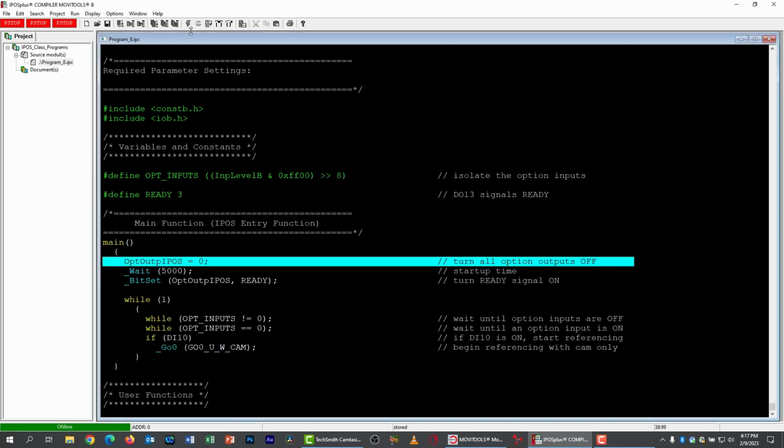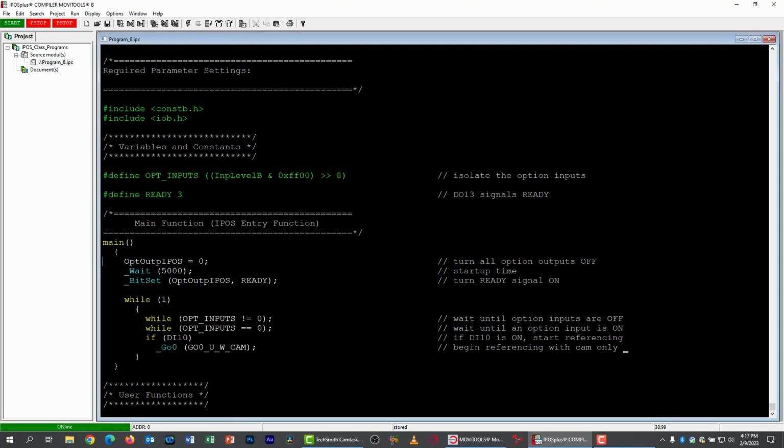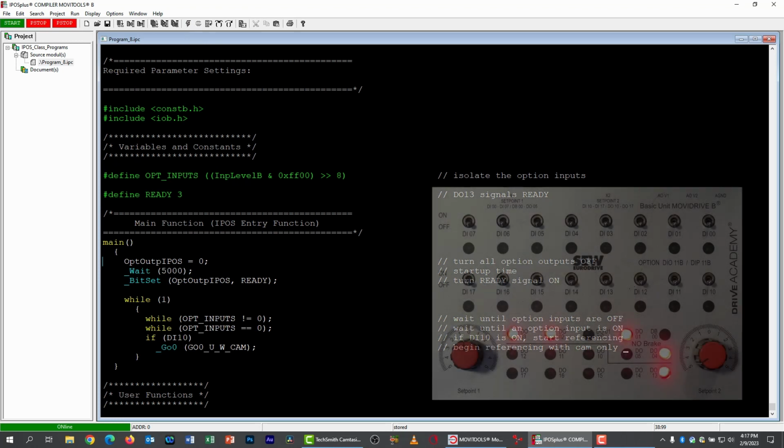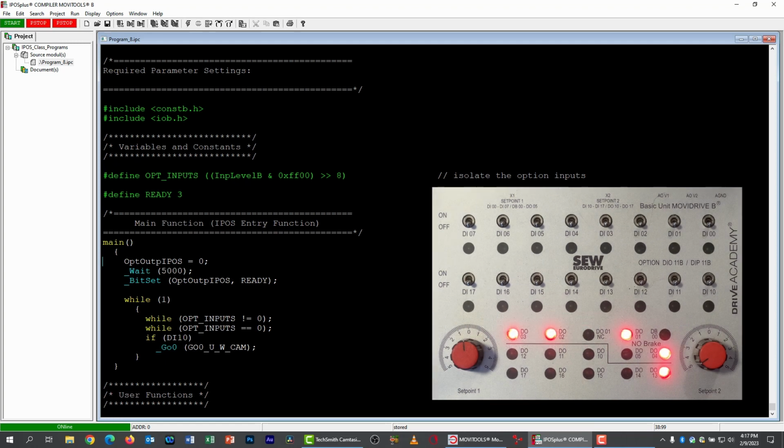And it is. We'll run it and go to our control box and exercise our program and see if everything works. This is our first program that produces actual motion. Therefore, we have to get our switches set up correctly for things to work right. As I mentioned, we have to remove controller inhibit from the VFD and enable it. We have assigned 2 bits to that. Controller inhibit is permanently assigned to DI00, but we've assigned enable to DI01. Both of those inputs must be on for the VFD to be able to produce motion.